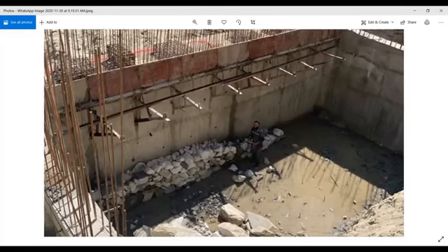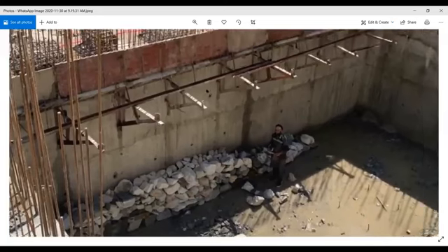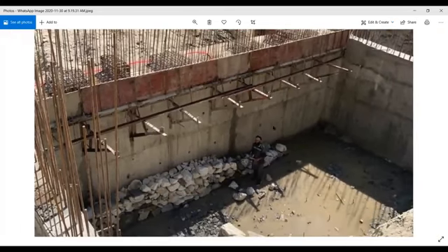On site, you will actually come to know how is this shuttering done, because this entire foundation is not poured in one go. As you can see this mark here, this was the first lift, and then as you can like the shuttering is done here, they would have put the boards here at this location, and then these arrangements they would have come at this location, so that concrete for this location would be done.